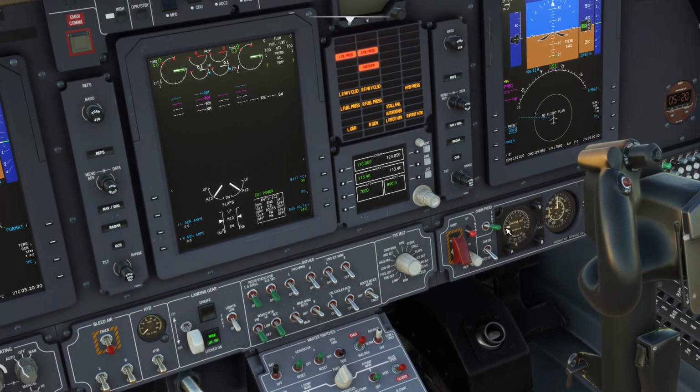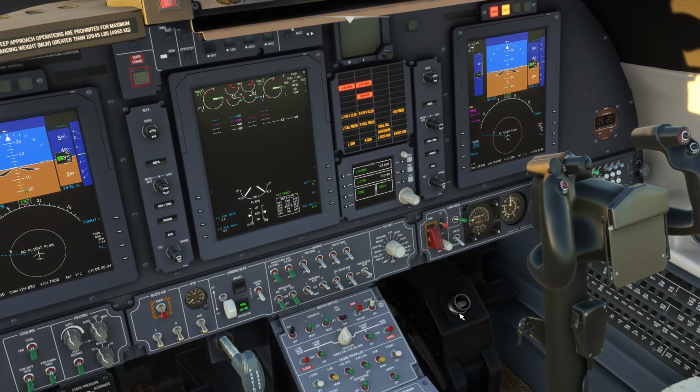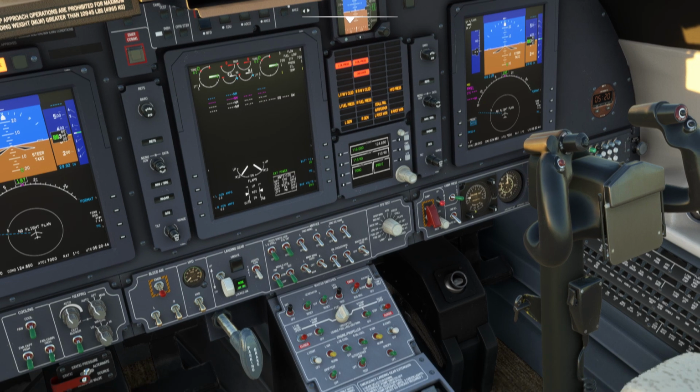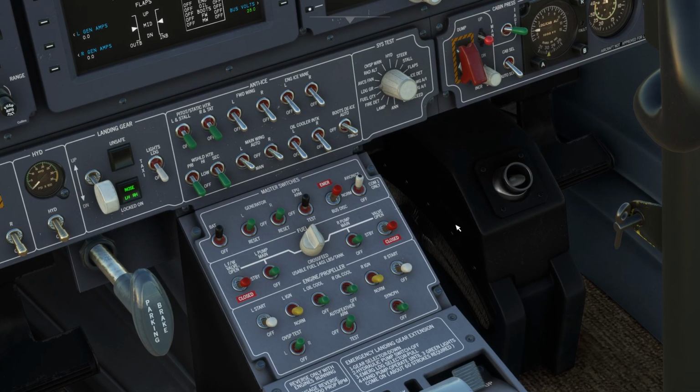That's because of the connection to generator and energy saving, but because we have GPU plugged, we will get it to ARM, and our standby altimeter comes to life as well. EPU is installed to provide power for flight critical equipment in case of bilateral generator failure. Bus tie switch, which is this one, and that one should be on norm. Is it? It is. Right.